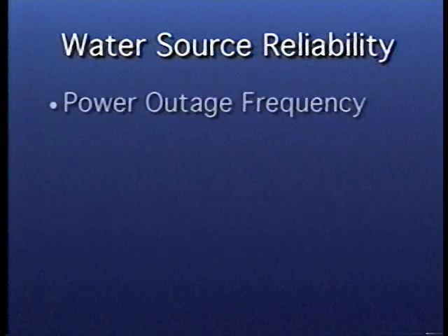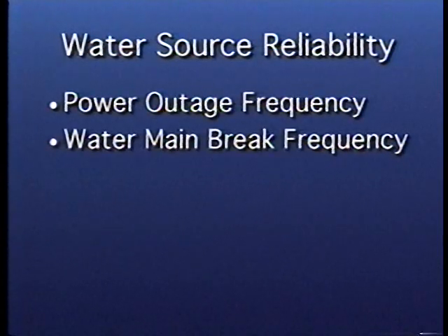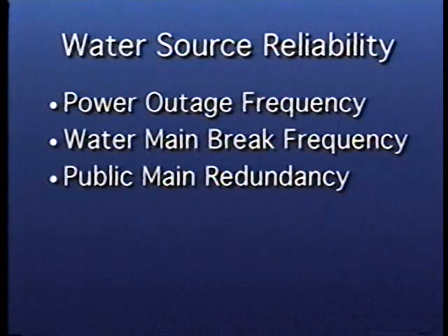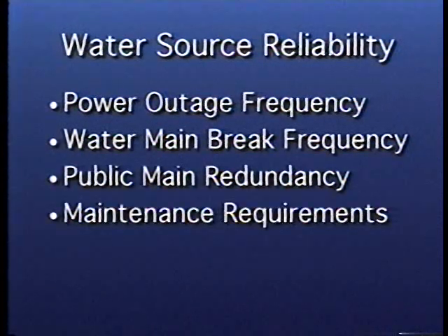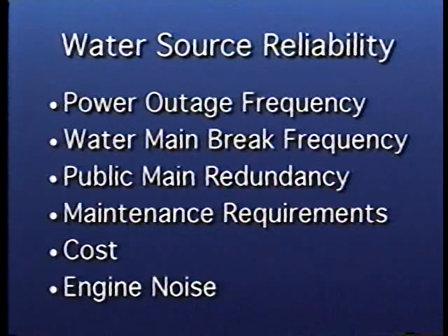Several factors must be taken into account when assessing the reliability of the water source: frequency of power outage, frequency of water main breaks, redundancy or gridding of the public main, maintenance requirements, cost, and noise from diesel engines when running weekly tests.